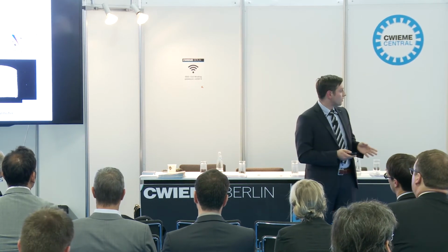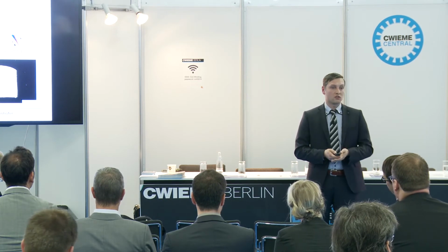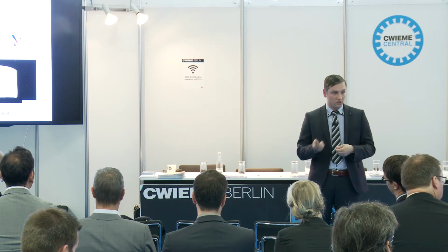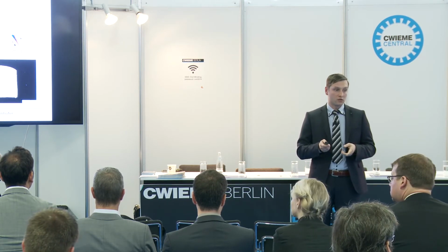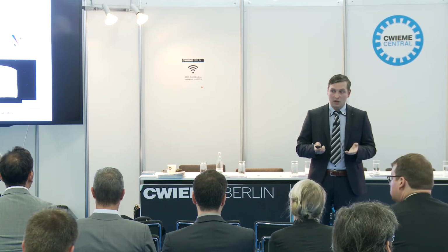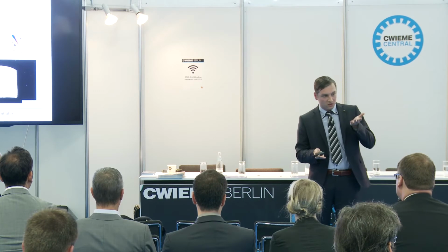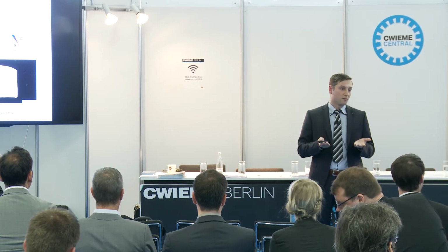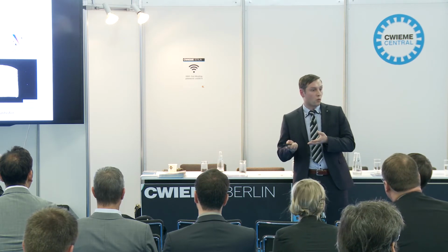Of course, you can get a smoother cutting edge if you decrease laser power or increase the cycle time, but that also decreases the output performance, the cutting speed. I'm telling you that because you always have to adjust your approach according to the product requirements, output versus tolerance requirements.